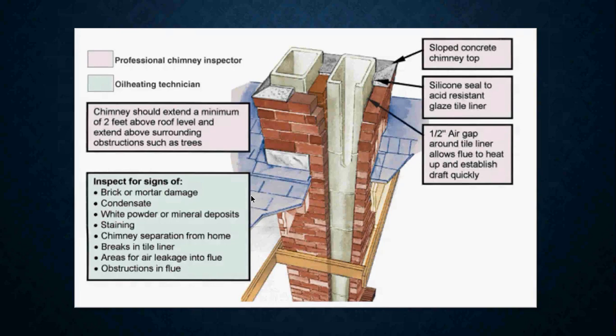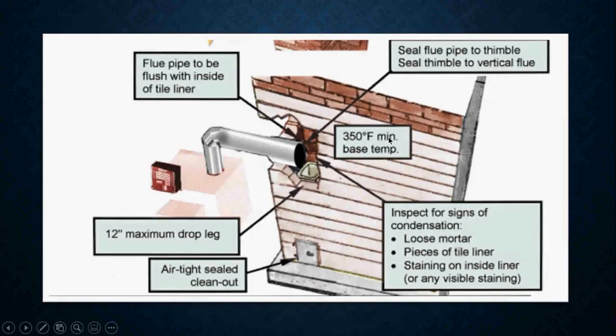But you, as the oil heating technician and guru that you are, are going to make sure that you are inspecting your brick and mortar, making sure it's not damaged. You're going to make sure that there's no signs of condensate. You're going to make sure that there's no white powder or mineral deposits inside it. You're going to check for staining, all those sorts of things. You want to make sure that it's all in relatively good condition.